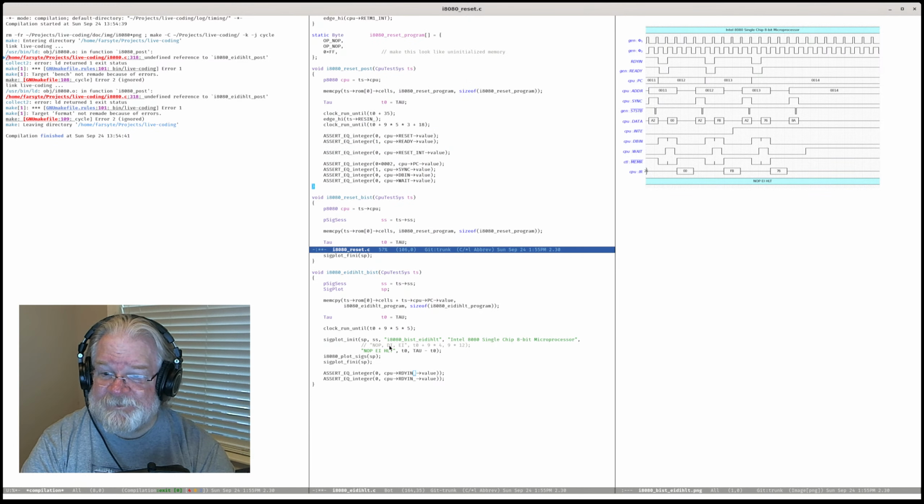So if we change our program that we're running here for this test, this value will be different. And I think actually we need to set it based on the initial value here. So word PC0 is equal to, and this is 11, so PC0 plus 3, I guess. We'll find out the first time that runs. So PC is set to there.